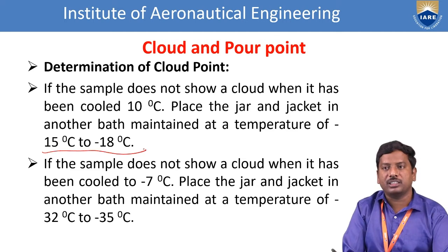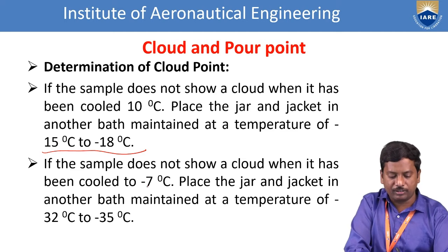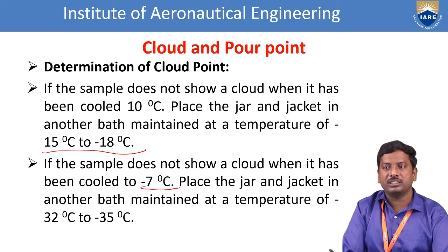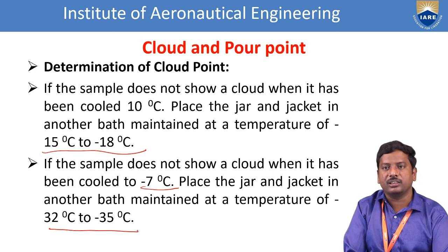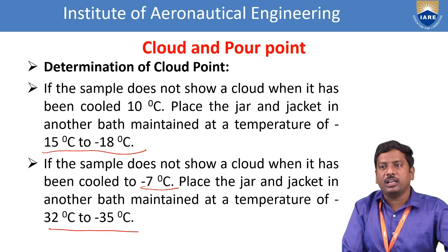If the sample does not show a cloud when it has been cooled up to minus 7 degrees centigrade, now place the jar and jacket in another bath maintained at a temperature of minus 32 degrees centigrade to minus 35 degrees centigrade. This condition is possible in the case where the oil does not show any clouding.